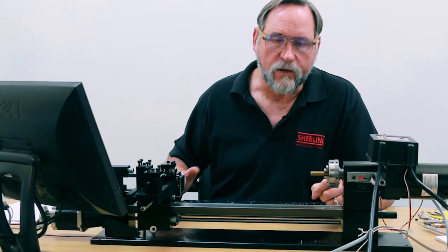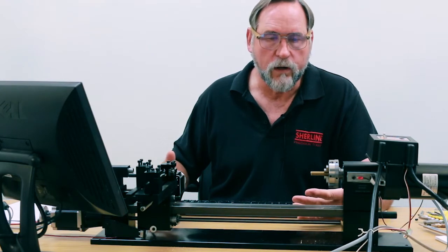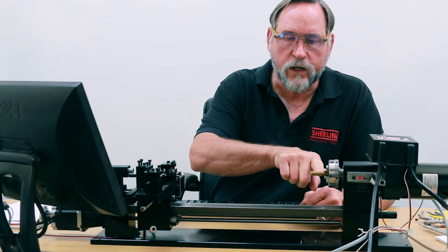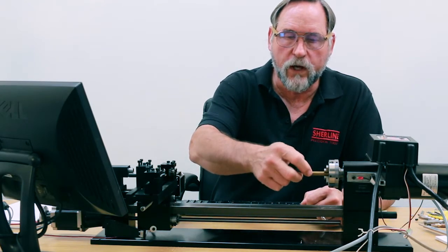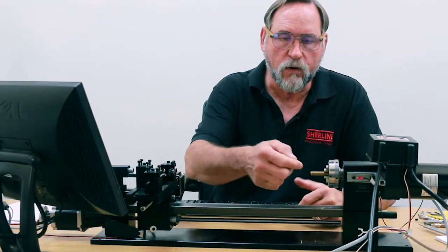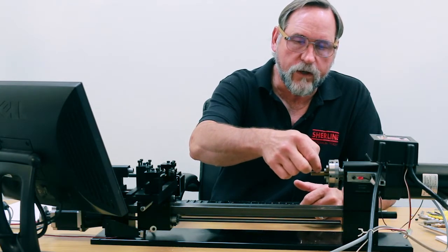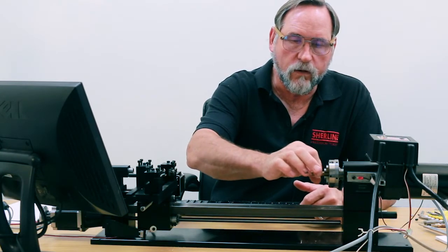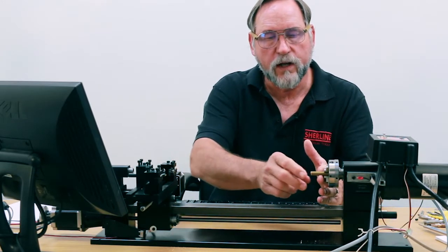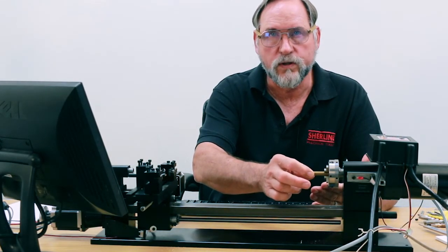Now, if you program your part in CAD/CAM software and give it this shape, with the diameter brought down to 1/4 inch and a full diameter ball cut on the end, the program would want to rough turn the ball, and rough turn and finish turn the 1/4 inch diameter. Then you have a very small diameter and you're trying to machine out at the end. So this makes it even worse.